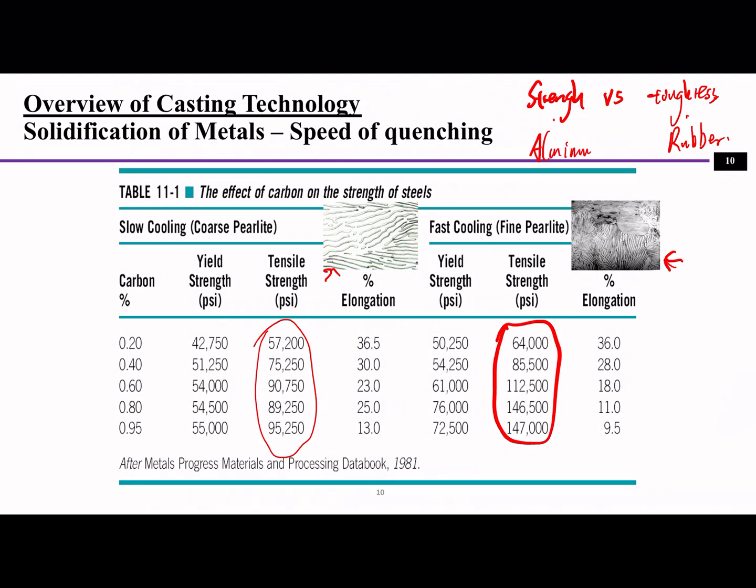for rubber, when some external force starts to apply, the rubber will deform. So when it's deforming, there is a release of stress in the material. If there's no deformation, there's no release of stress, and stress will be concentrated at a certain place, and that's why it will easily cause fracture. But when it deforms, it will release the stress, and that's why it will be more tough before fracture. To make sure you understand the difference between strength and toughness: in most cases, strength and toughness are mutually exclusive. Okay?